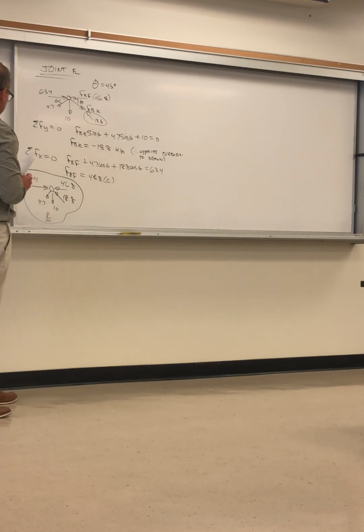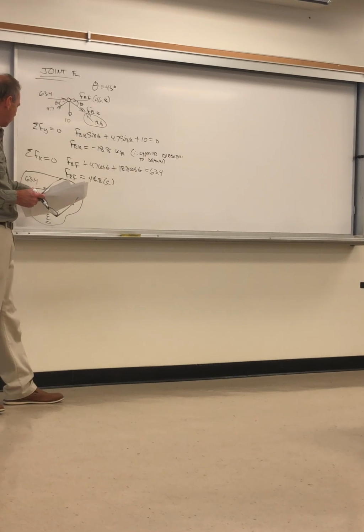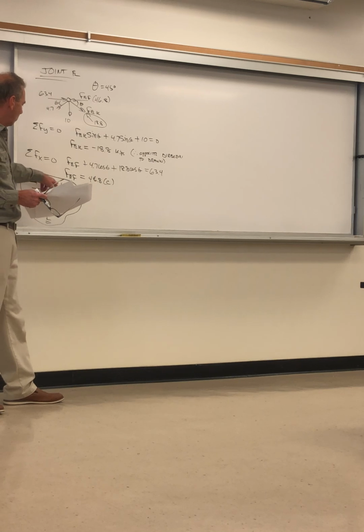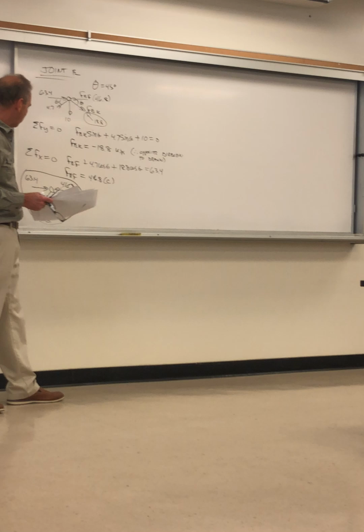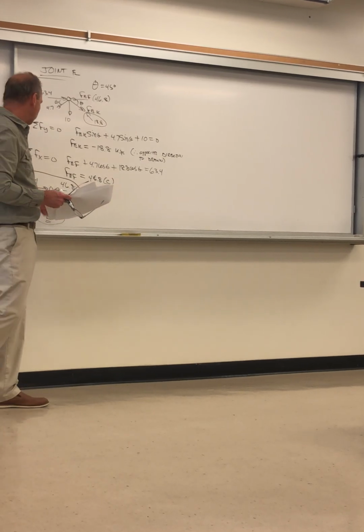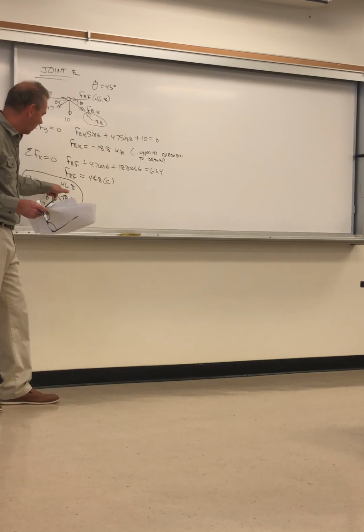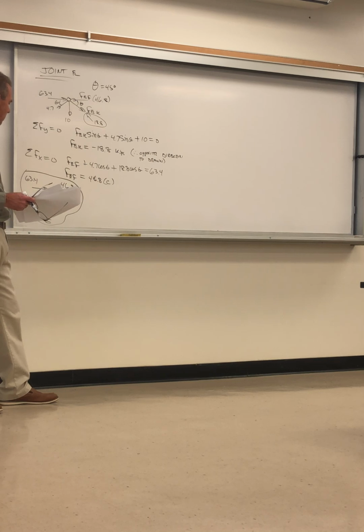Center transfer. Let's take a quick look, make sure it looks reasonable. So I've got about 3 this way, 40 this way, another 10 or 15, 46, 56, and 60. That looks balanced horizontally. Vertically, I have now this 18.8 going in that direction, some compression. So the vertical component is about, let's say, 13 to 14.